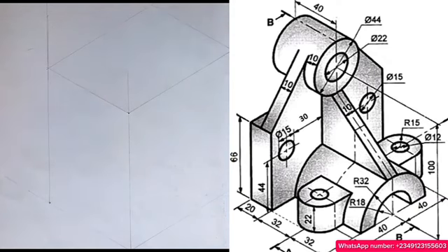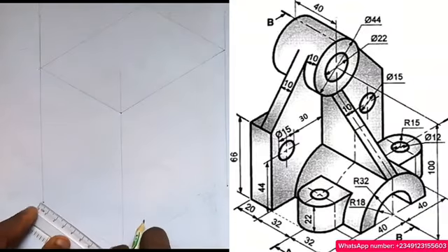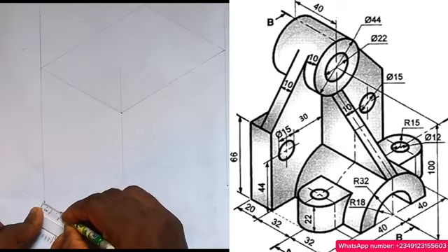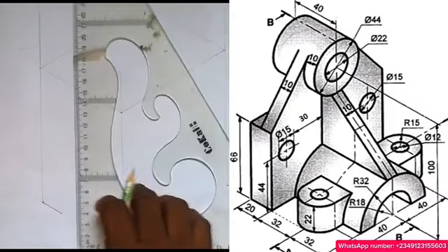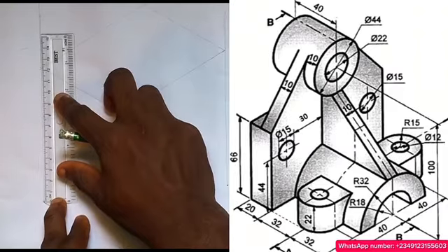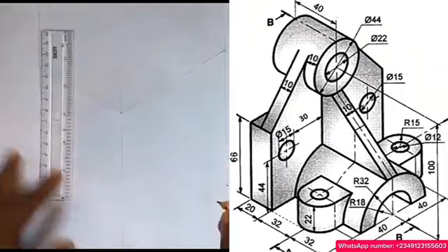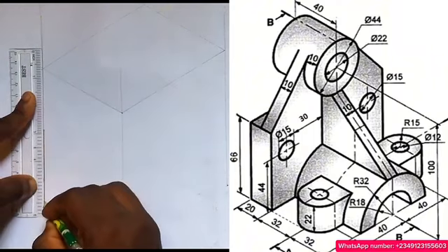So it's from this figure now that the isometric is obtained. Let's start by producing our first task. Observe that at the back here there's a length of 20. I'll measure 20 from here to here, and tick it. Of course, there's a height of 66. So measure 66 from here to here, and it's ticking, so I'll thicken it this way.